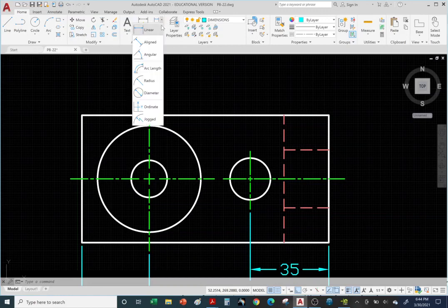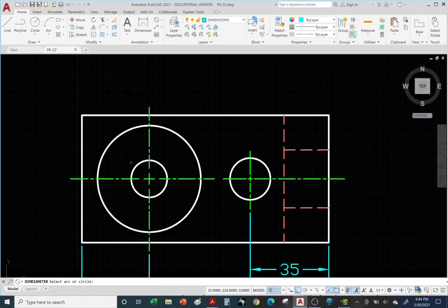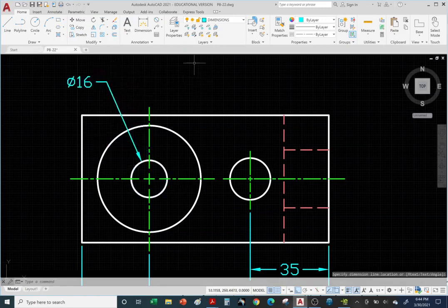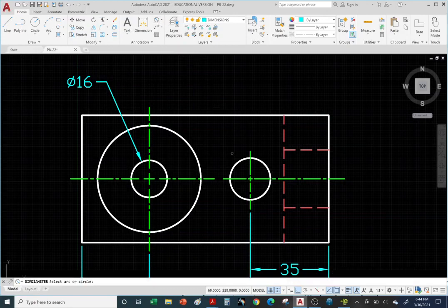All right, so if it's a complete circle, you go with diameter, right? And it has to be a hole. There it is. Place it. Go to the next one. Click on it. Oh, I just realized that I have Object Snap turned on. No wonder I was getting a little bit of snapping. So let me turn off Object Snap or Snap to Grid. There it is. That's the reason I was having issues on the previous videos, misclicking.